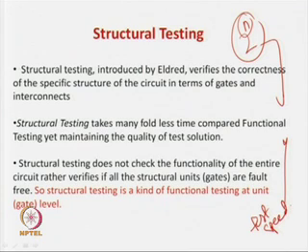We can move up the test speed, but fine, you can go up to megahertz, you can go up to gigahertz, but going to terahertz or even higher will require a tester which will be so expensive that you can never make a profit by selling the chips. We can make a profit by selling the chips if the yield is low, that is, if 50% of the circuits are defective, you can throw out 50% of the chips and sell the other correct 50% in the market, and you can make a profit. That is absolutely fine.